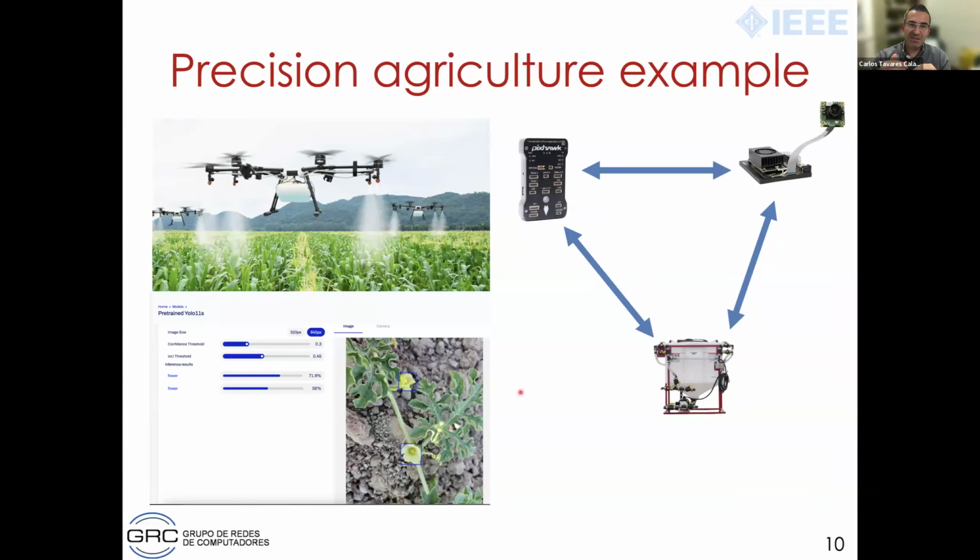Then on top of that, we are obviously developing our own protocols. And the slide I have here is in fact quite useful. Why? Because what we have right now is that we introduce an embedded system, usually a Raspberry Pi, and the embedded system is connected to the flight telemetry so that we can talk to the flight controller and have this bidirectional feedback.